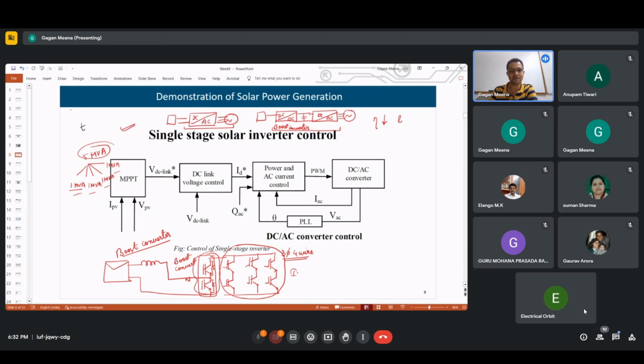We can control this DC motor to act like a turbine. Because it is DC, we can control it using a chopper, which is a DC-DC converter. How should we control it? We need to vary the duty cycle of the converter, and how the duty cycle should be varied is decided by the algorithm inside the FPGA controller.